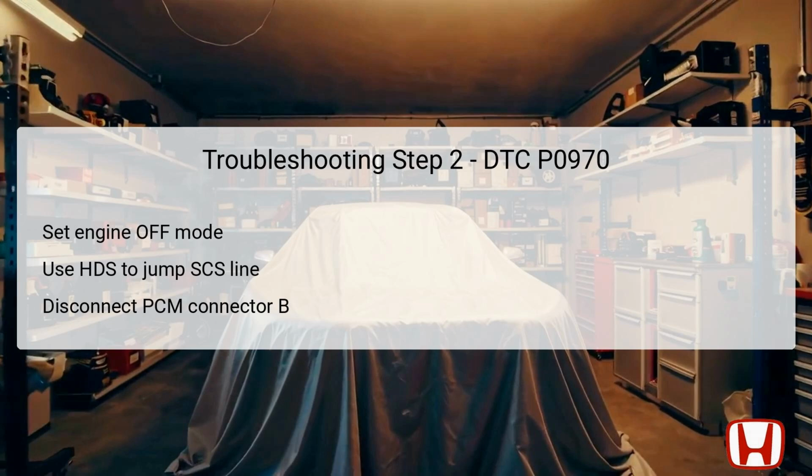You will then proceed to check the continuity between designated test points to evaluate whether there is a short circuit in the LSC line. The test condition is crucial here. Ensure that the vehicle remains powered off. Understanding the significance of each action during this step will greatly enhance your troubleshooting efficacy.